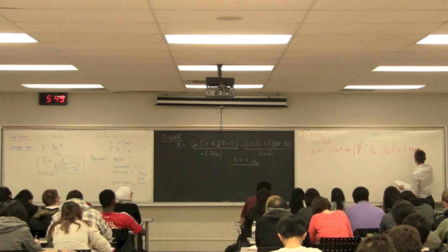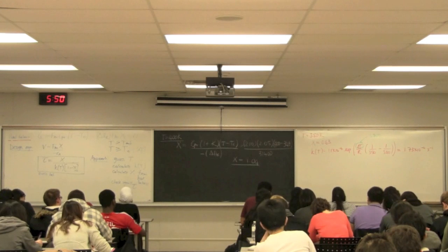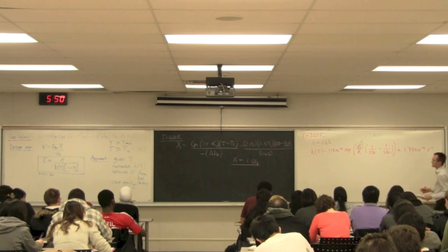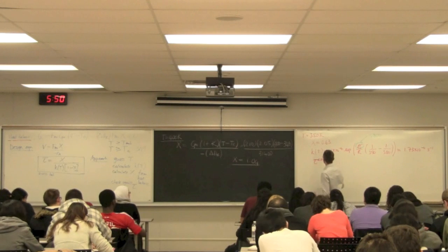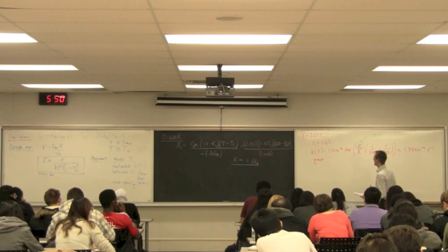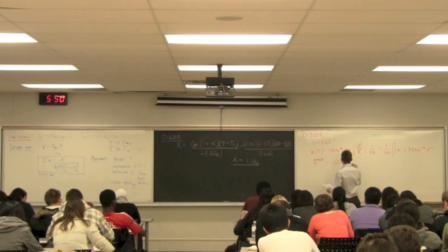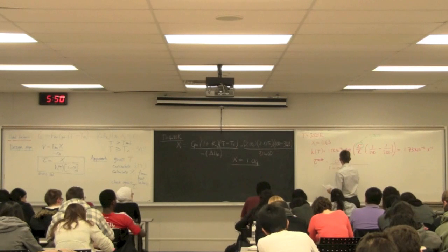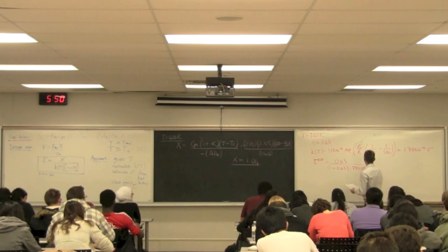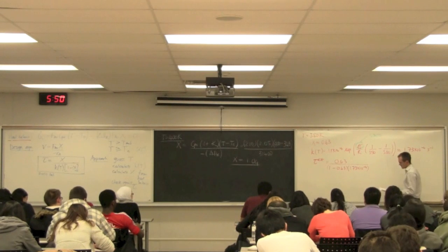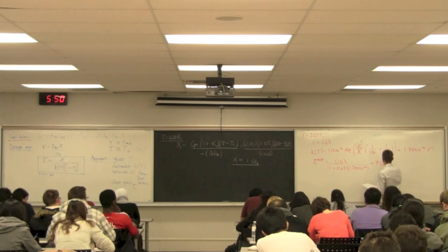So that calculates at 1.73 times 10 to the minus 4 seconds to the minus 1. So then if I sub into that mass balance over there, I'll get tau. Let's call this tau estimated. We know that our tau should be 600 seconds. But let's see, with this guess, what we estimate tau to be: 0.63 divided by 1 minus 0.63, multiplied by 1.73 times 10 to the minus 4 from that rate constant. So that gets me an estimated tau of 9,842 seconds.